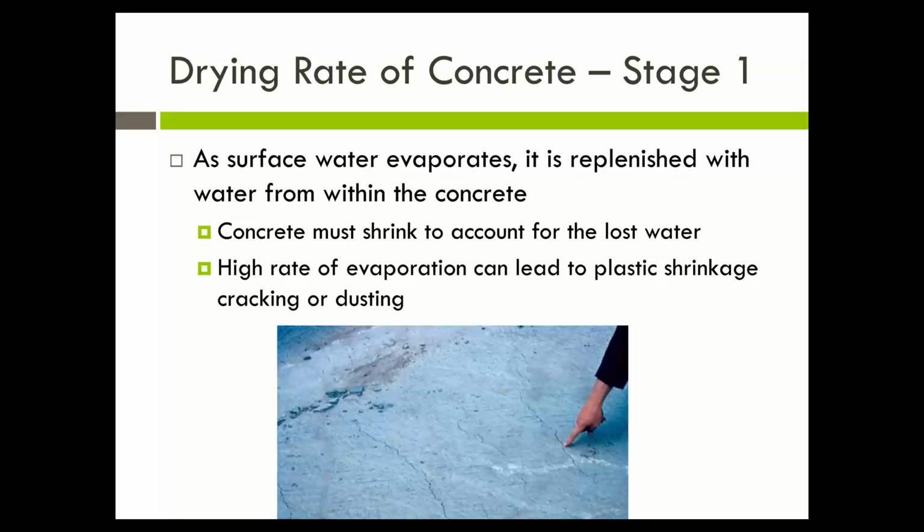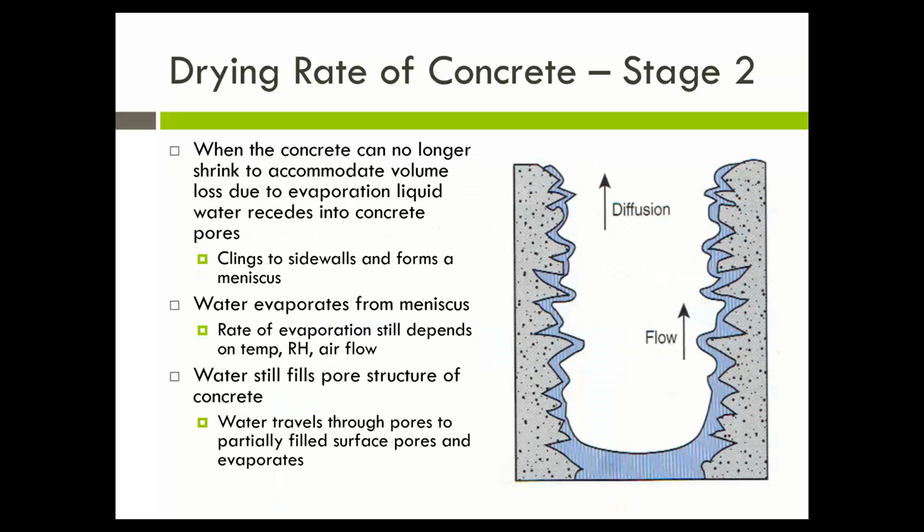They start up and they stop, and they're not very straight. These occurred while the concrete was still plastic. The other thing that comes along with this is that we remove the water from the very surface paste, and as a consequence, it isn't very strong and it will dust forever. So these are the things that can occur. We get our high rate of evaporation, but the concrete is shrinking as we take this water away.